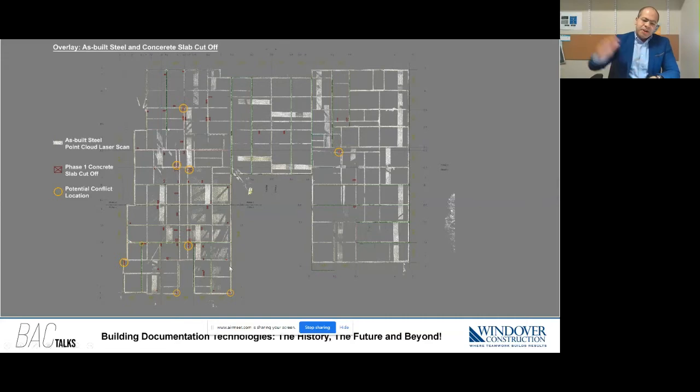After we erect steel, we capture the data with the LiDAR, with a laser scanner from the air, and complement that with laser scanning from below to capture a highly detailed point cloud. And then we do real-time, same-day overlays to detect clashes with what the factory in Canada is actually planning to do with their vertical shafts. And we found in real time a few clashes: if they put the vertical shaft in the modular box and ship it here, it's going to hit some steel, because every inch makes a difference on the steel that gets erected.